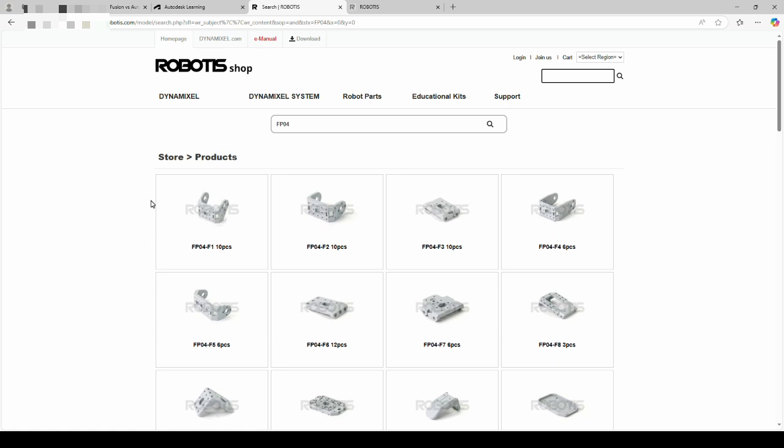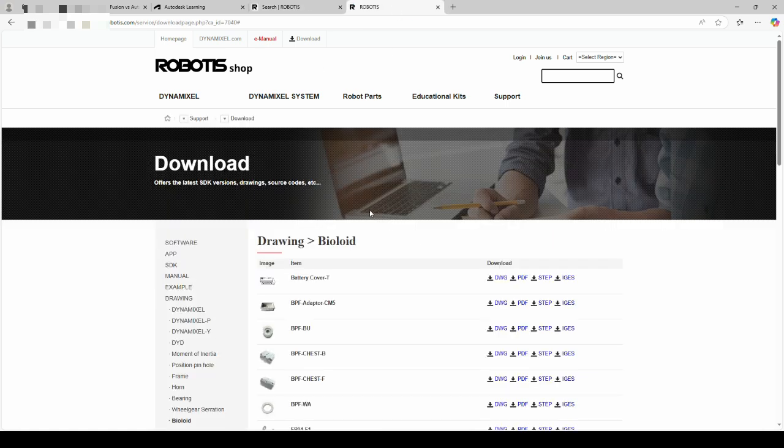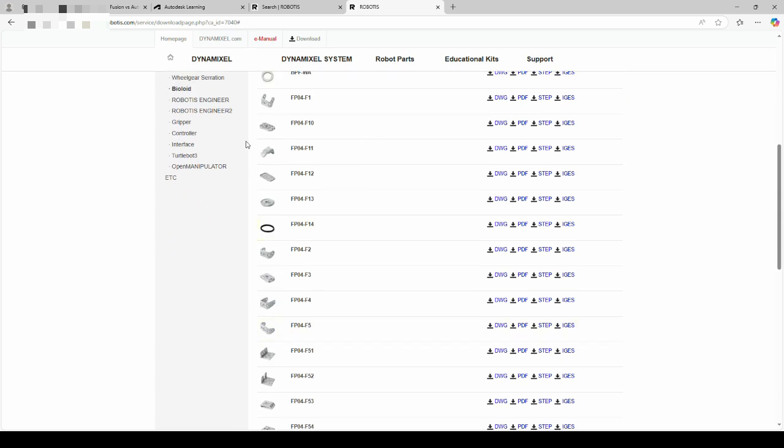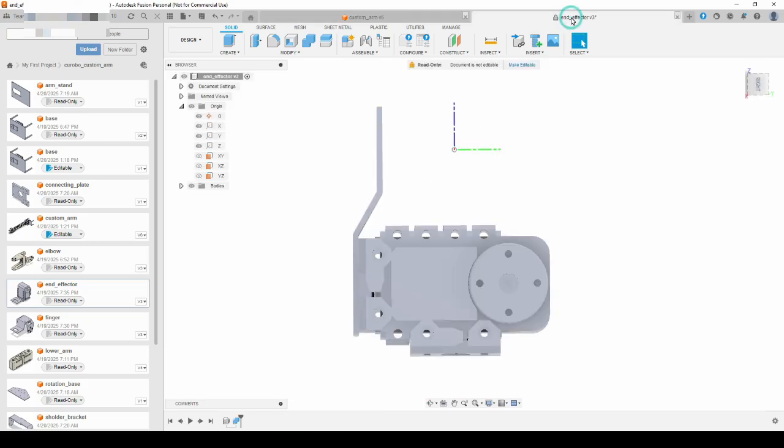Since drawing every part is time-consuming, if there are publicly available CAD files, I recommend using them. For example, in the case of robotics products, there are CAD files available for almost all products. If you design your robotic arm for manipulation, it is good practice to set the origin of the end effector at the point where you assume that the gripper will hold the object.